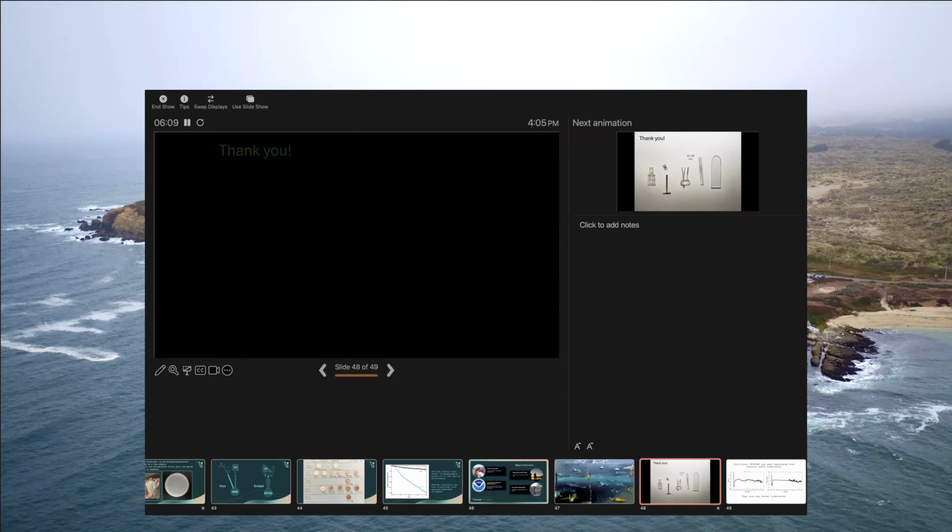Can I jump in on that one? Do you have a library of images so you can actually identify and count? Yes, we're getting there. We're developing a library of images, and then you can train machine learning models to process the data on board the Minion. That's where we're really trying to move toward, so that we don't have to send back full images. One image right now costs $1,000 in Iridium costs, which is equal to the cost just to get one full resolution picture, which we wouldn't do, of course. We'd do some sort of compression, but just as context.